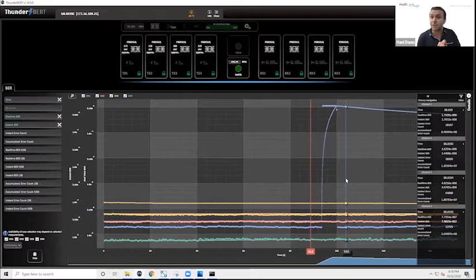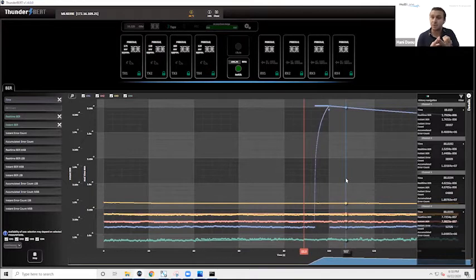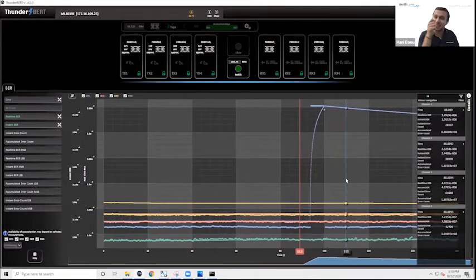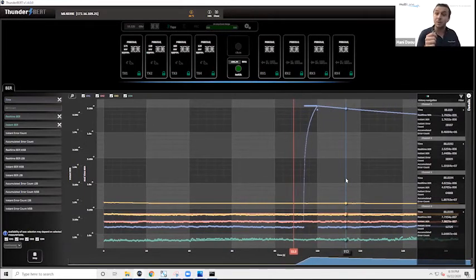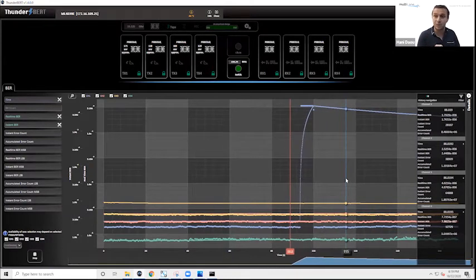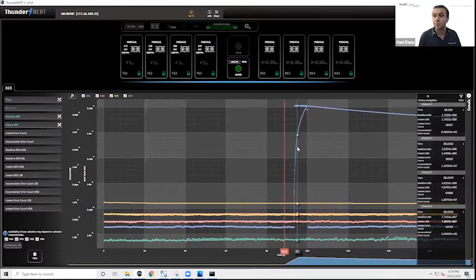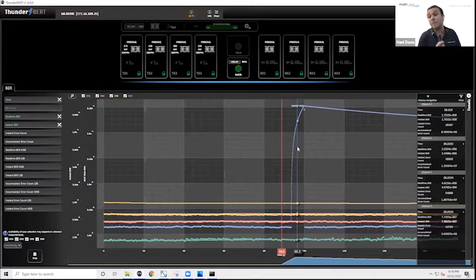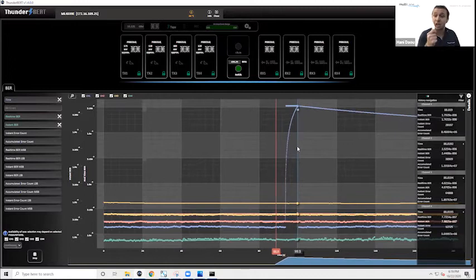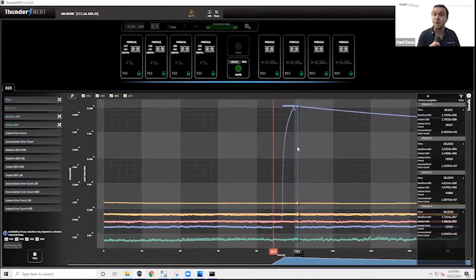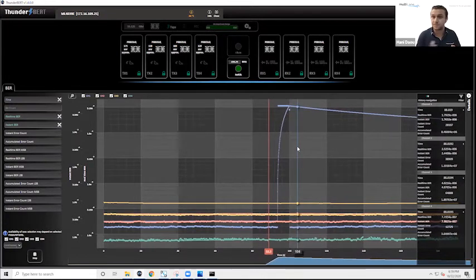So any measurement offered in Thunderbird can be captured in both real-time or instant modes. Real-time being cumulative, instant being in that 100 millisecond time constant, what was the error profile? And error bursts require this type of advanced error tracking. These error bursts, like the one that we forced, are the difference between a strong transceiver design and a marginal transceiver design. And we are giving this visibility to be able to diagnose transceiver marginality, both to the vendors and the consumers of these high-speed products.